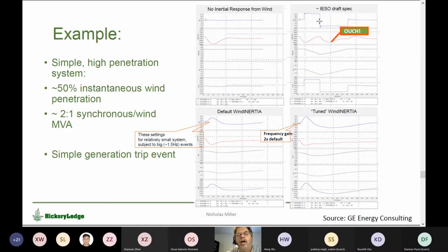But then when we get the recovery backlash, we get whacked again. So that's a pretty ugly outcome. This recovery over here is almost as bad as the initial event, and that's quite disturbing to the system. Damien and Lisa showed conditions where this backlash is actually even worse. If we just take that GE block diagram that I showed earlier, you get a much better outcome. The depth of the frequency excursion is improved, and the frequency comes back in a relatively orderly fashion. Closed loop controls are easier to get right than bang-bang open loop controls. So that's a learning exercise.